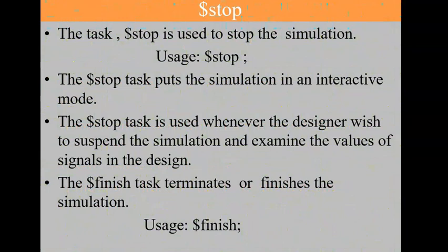Similarly, $stop. So $stop is the task. $stop means it will stop the simulation. Remember, I use a very normal word, temporarily. Just like I told you earlier, $monitor on, $monitor off. Here, instead of that, I use simply stop. That means when a simulation is going on at 100 units of time, I want to note down the result. Then I use $stop at 100 units. That means the simulation will temporarily stop.